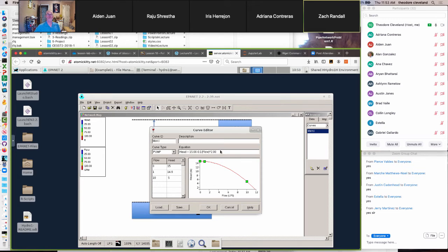You'll notice it tries to provide an equation. And in this case, the equation it provided is an exact replica of the equation we wanted to use. But that won't always be the case. So if I put in an 11 and a 4, it can't fit the equation, although it can still render and approximate a pump curve. Once we go beyond the 3-point curve, it's not well suited to estimating an equation.